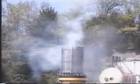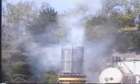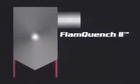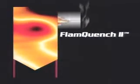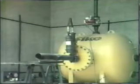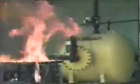Flameless venting is an efficient way to reduce the maximum explosion pressure for equipment located indoors. Using Fike's Flame Quench 2, process equipment does not have to be located near outside walls to accommodate ducting and can be optimally located. Explosion isolation strategies may be combined with venting or flameless venting to prevent secondary explosions.